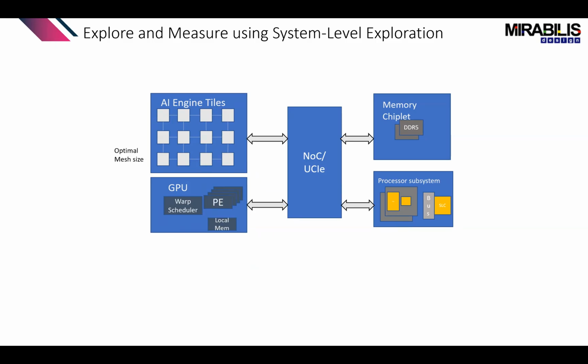When you look at your architecture, some of the key things when it comes to the interconnect are how many ports do you need? How many modules? What's your interface buffer? What's the quality of service? What's the interconnect speed? What's your optimal mesh size, that is, how many X by Y do you need? Being able to first answer all these questions becomes the primary motivation. And that's where today's webinar is focused, which is on the network on chip.